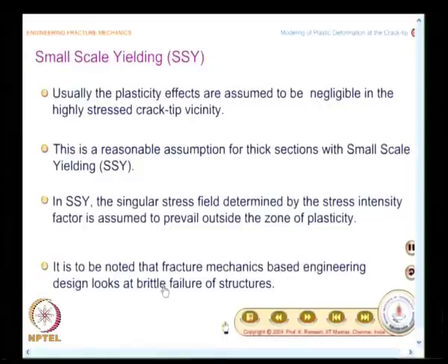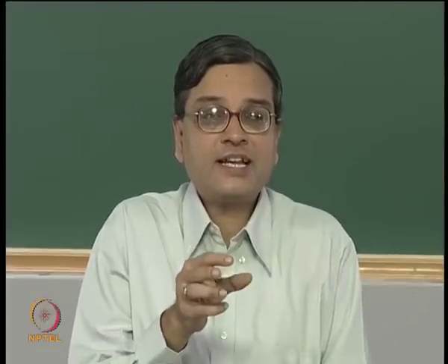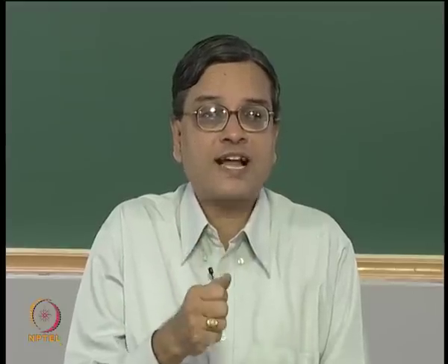And what is reminded here is the fracture mechanics based engineering design looks at brittle failure of structures. Structure has a hole, fails in a brittle fashion, but what happens at the crack tip, certain amount of plasticity effects also dictate what happens and how this is handled. That is the way we have to look at it.